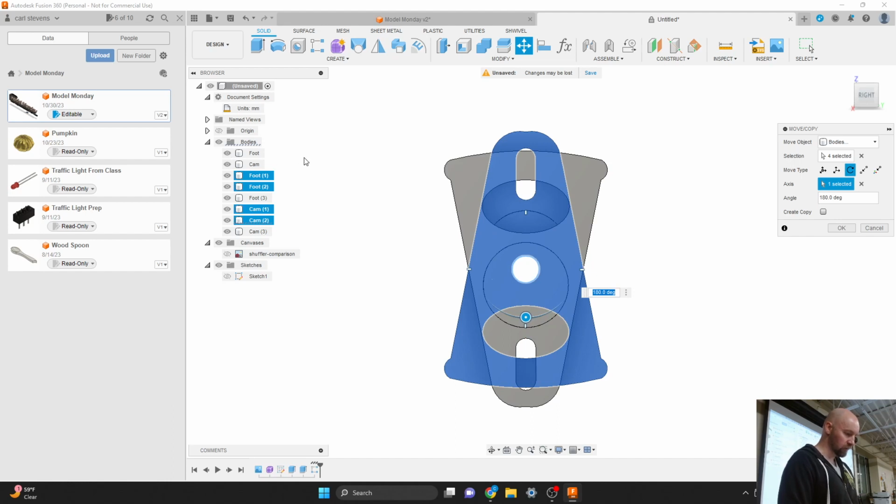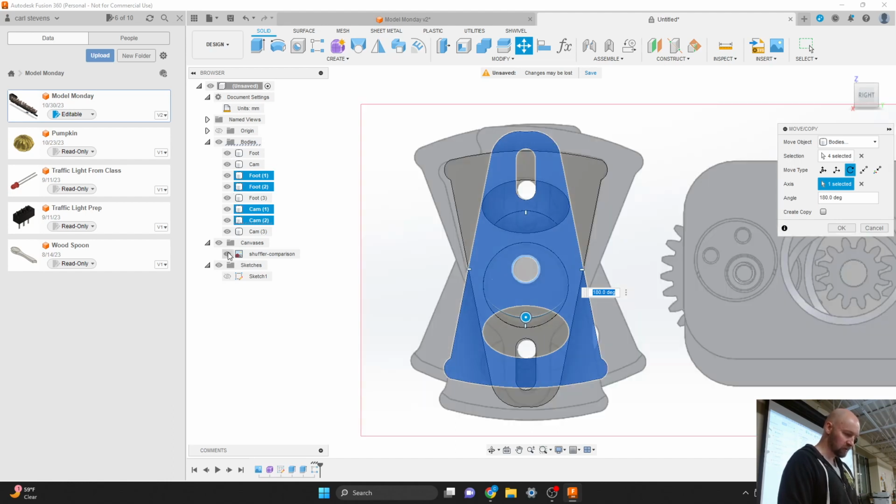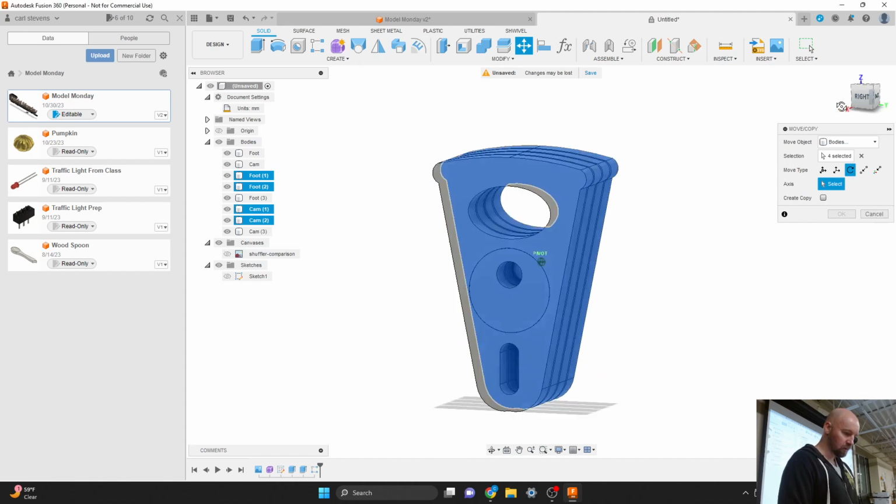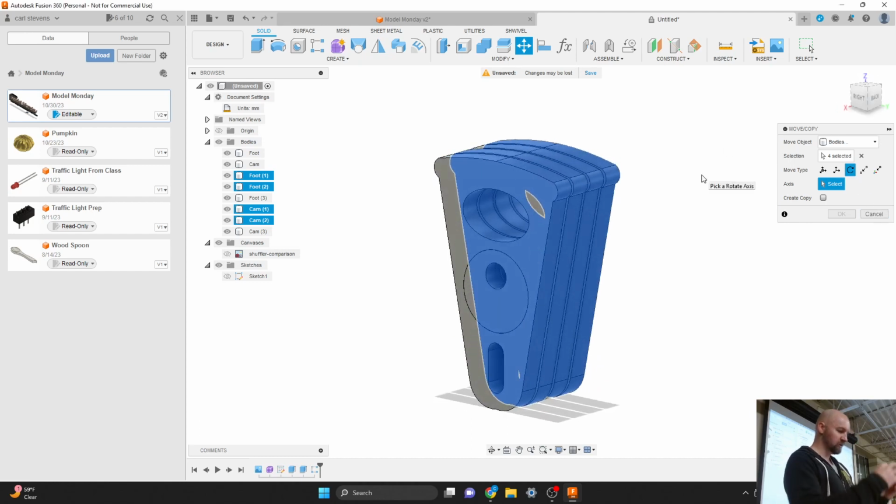I think that's how, here, tell you what, let's go back to this canvas. Yeah, because with this thing you want all the cams to be offset from each other, so each foot is offset. What's the camshaft going to look like? A bicycle wheel camshaft kind of thing? Well, I would assume they're offset from each other versus this is the center. This is where our motor goes. It attaches here. And then these things go up and down, and it lifts the foot up and down, right? Yeah, so if all your cams are lined up, it'll hop. And if you offset them, then it'll walk.